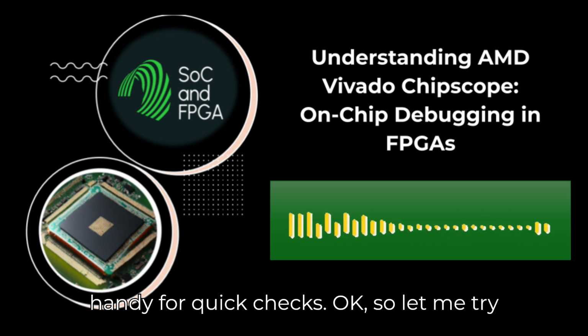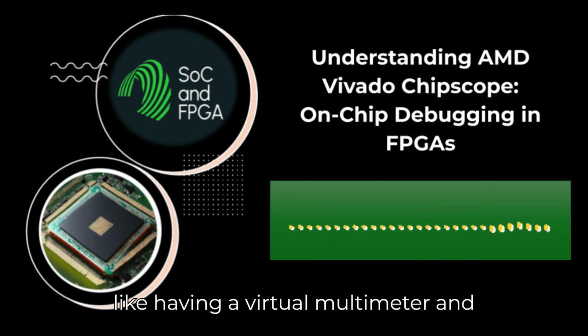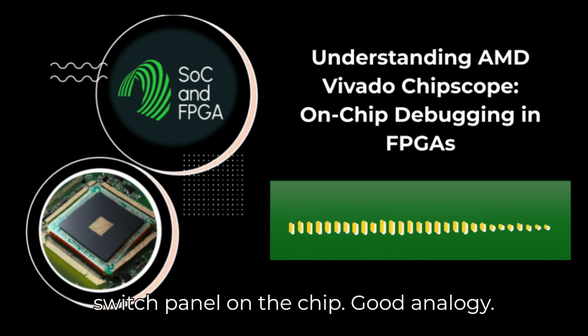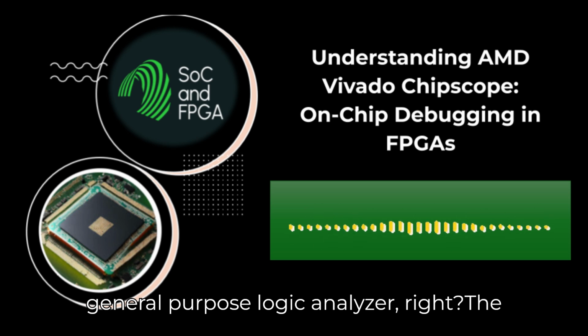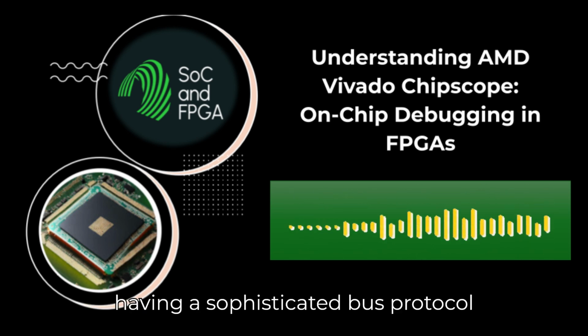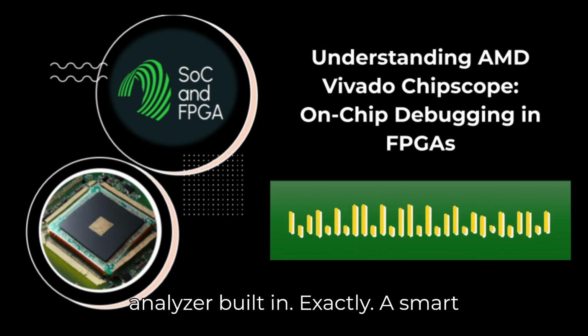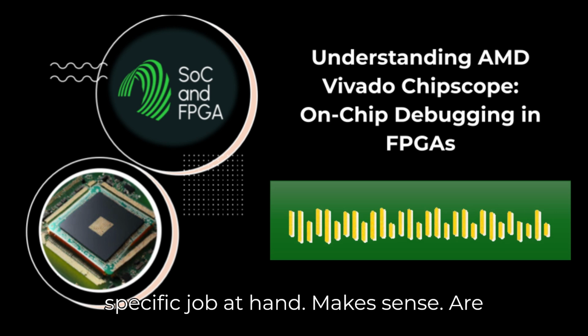Super handy for quick checks. Okay, so let me try to visualize this. The VIO is kind of like having a virtual multimeter and switch panel on the chip. Good analogy, yeah. The standard ILA is your powerful general-purpose logic analyzer. Right, the workhorse. And the system ILA is like having a sophisticated bus protocol analyzer built in. Exactly. A smart engineer picks the right tool for the specific job at hand.